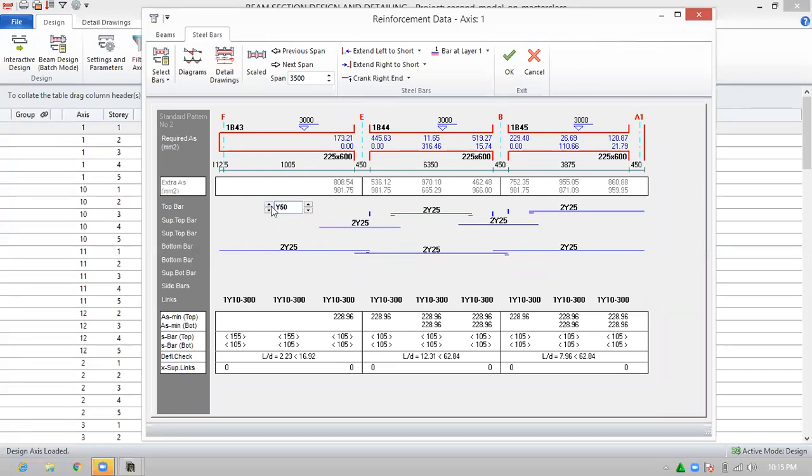You see the top reinforcement here. I'll click 1, 2, 3, 4. I want it to be 4, and I'll bring it down to 25. The corner reinforcement is 4 bars. This can be 3, this can be 3, and this can be 3. So the top bars, I want it to be 4, but I want this to be cranked. So I'll say crank at both ends.